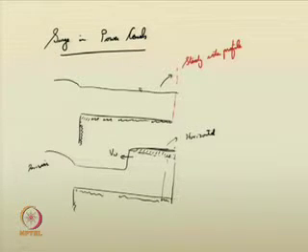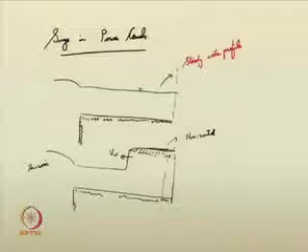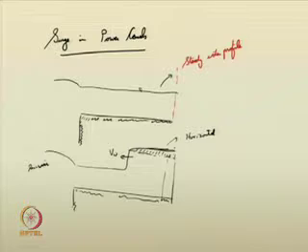You neglected friction earlier, but in this case, by incorporating proper friction as well as the slope of the channel, and considering this additional volume, you may see that this surge may not go with a vertical front and reach the reservoir entirely like that.